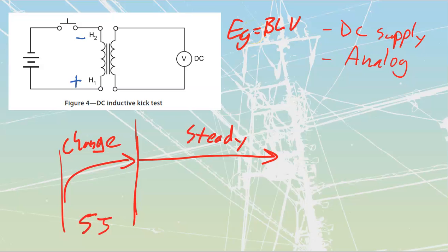I'm going to go and connect my voltmeter. Now your voltmeter does have 2 leads to it. Where we're going to have a red lead, the red lead goes in the red socket on there. The black lead goes into the black socket on there. If you mix up which one it is, they're always referring to what the socket is. The rest of that is just your mistake. So we're just going to make the assumption from this point forward, you've got the black lead in the black socket, the red lead inside of the red socket.